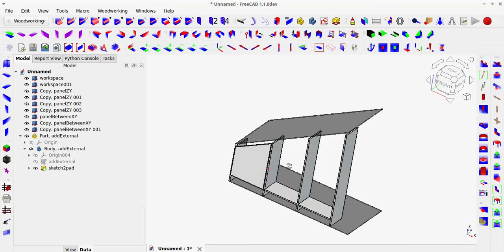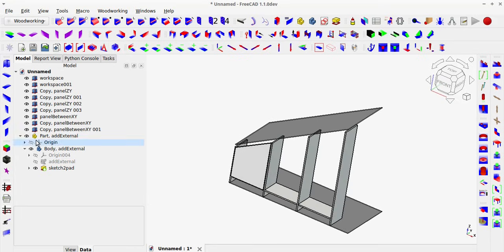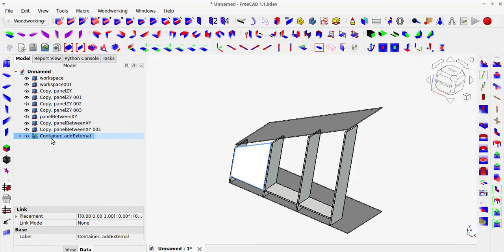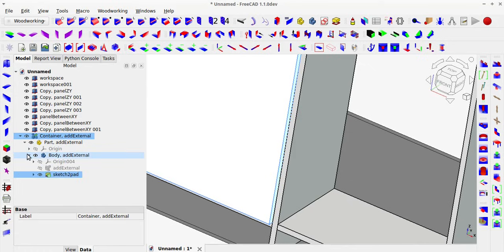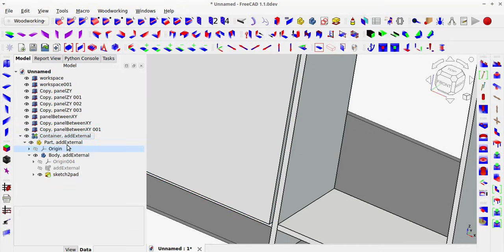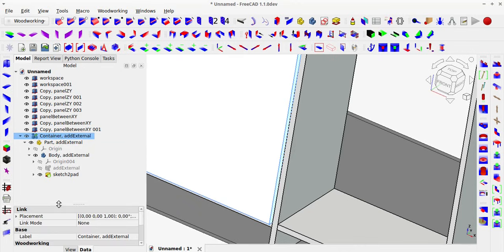By default, fronts can be opened using the magic angle tool by simply rotating the element around the Z coordinate axis. However, I've also added an additional tool called Fronts, Open Close, dedicated to opening and closing fronts. The tool searches for all simple panels whose system name begins with front and opens them to the left. You can also select the right edges to override the automatic opening of fronts by setting attributes for a given front. These attributes can also be manually changed.